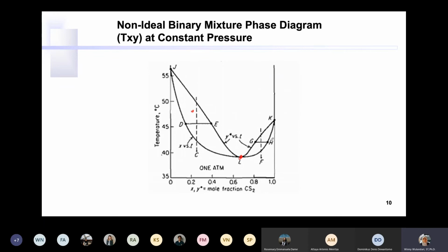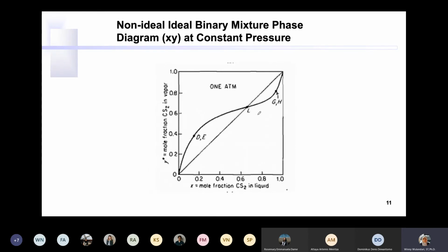So that's why there is a topic called azeotropic distillation, but it's not covered in this course. It is a technique for dealing with an azeotrope by adding another component to the mixture to prevent the azeotrope, because otherwise you really can't get past this point. In a distillation with an azeotrope, if you start from here, the range of separation is only up to here, and if you start from here, for example, only up to here or here. So there are two different areas for doing distillation.